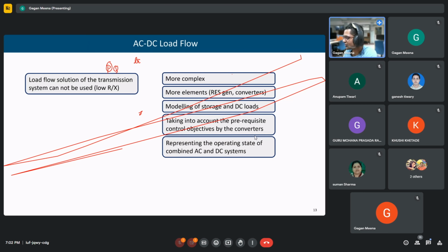But when we are working with a distribution system, each load type we have to consider. There can be different types: constant power, constant impedance, constant current load, or even the mixed ZIP model. So there can be a proportion of constant impedance, constant current, and constant power. That is why it is called ZIP.